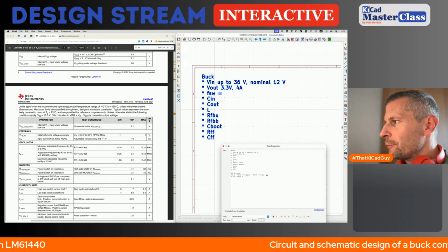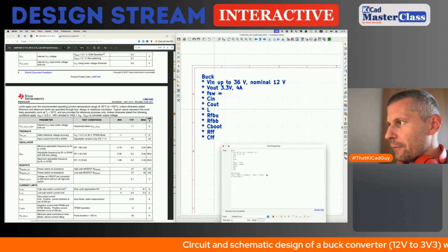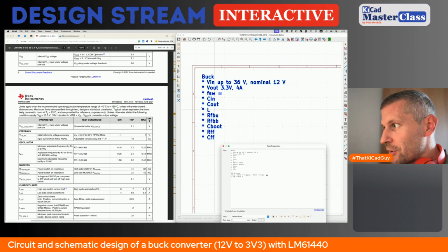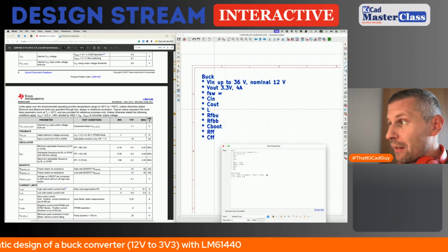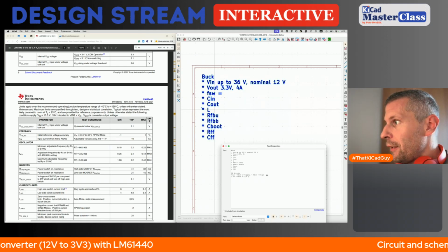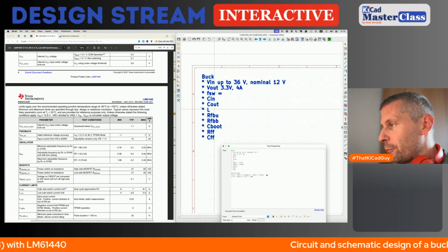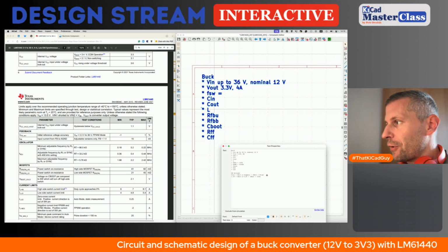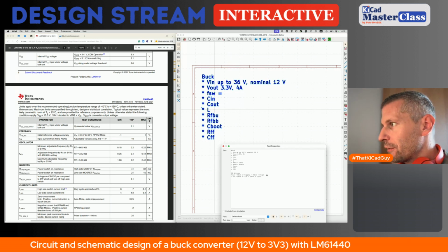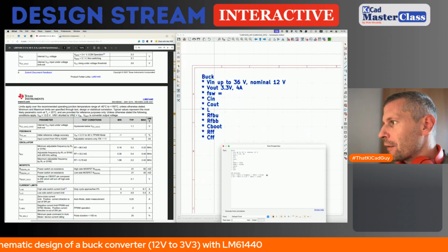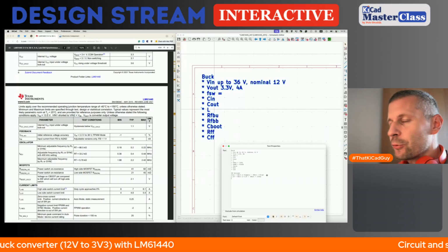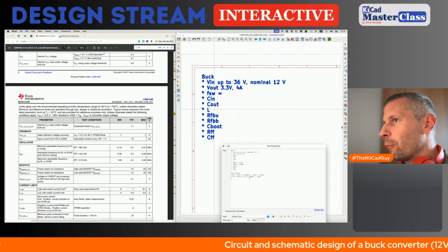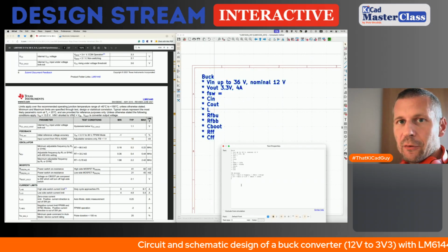Power supply is, no, I made a mistake. The output voltage of the divider is 1 volt. This is the feedback voltage. Supply is the output voltage of the converter, 4.2, divided by the sum of bottom plus top. We said that we chose the 100 kilo ohm as a top resistor. So there is a simple calculation. I don't want to continue, but you know that the value will be probably like 36 kilo ohms or something.